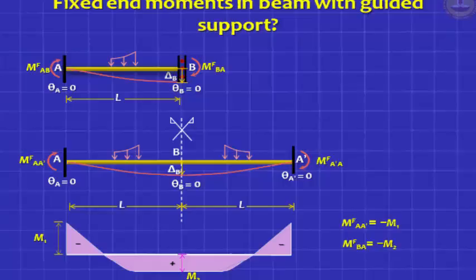Okay, so you'll also get a fixed end moment at the guided fixed support. Please note, it's a sagging moment. Okay, so in this fixed beam, you get two moments. You get M1 and you get M2, and you have to plug in those values in your fixed beam.